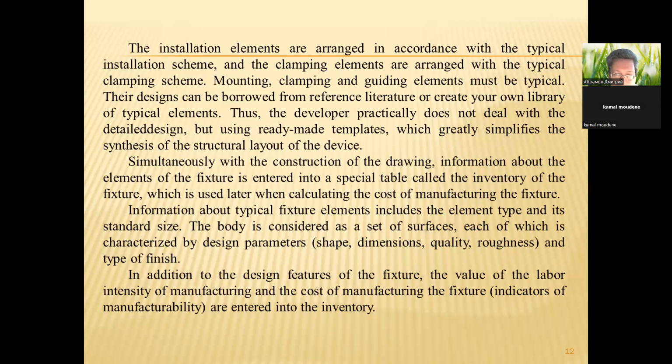The body is considered as a set of surfaces, each of which is characterized by design parameters: shape, dimensions, quality, roughness, and type of finish. In addition to the design features of the fixture, the value of the labor intensity of manufacturing and the cost of manufacturing the fixture, indicators of manufacturability, are entered into the inventory.